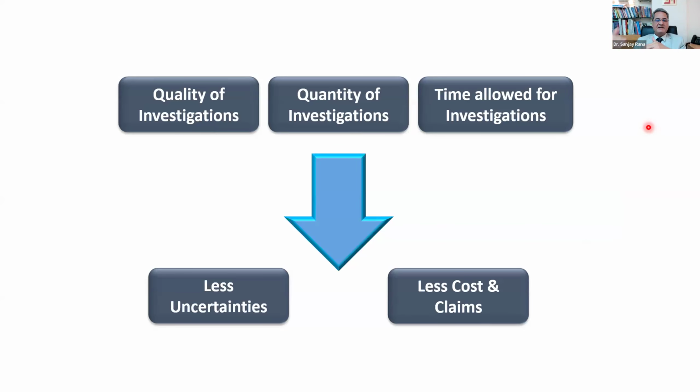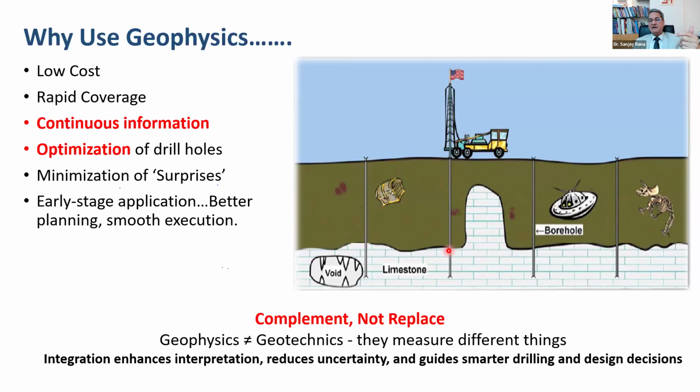And then next is optimization of drill holes. Geophysics does not replace drilling. Very, very important message to understand. It complements, does not replace. Geophysics is not equal to geotechnics. They measure different things. When you integrate them, it enhances interpretation, reduces uncertainties, and guides smarter and targeted drilling.